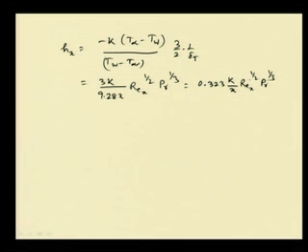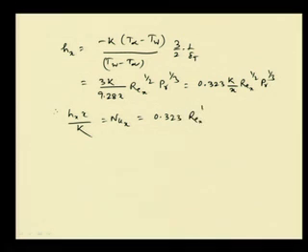Okay. So, h x x by k becomes Nu x, called the local Nusselt number, and this is 0.323 Re x to the power half and Prandtl to the power 1/3.